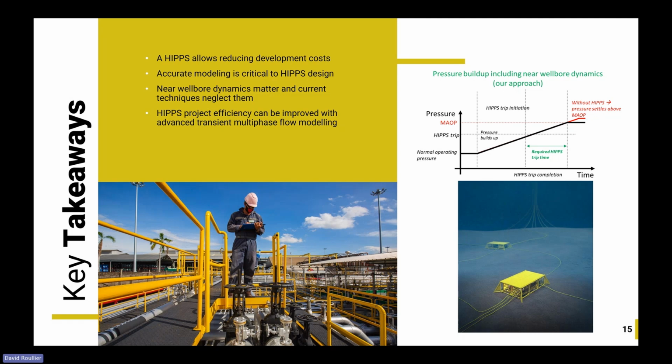Applying this method for that specific design, it can be that your bottom hole pressure drops below that reservoir pressure, and that drop will give you added time to react when compared to just assuming you have a constant reservoir pressure there. So it's true, the depacking could be the sizing case, depending on safety standards and whatnot. It often is, and the impact of this tool would be different for that scenario.